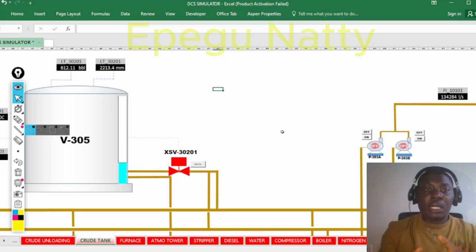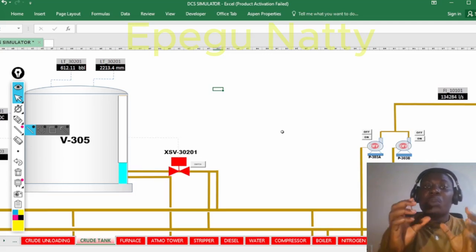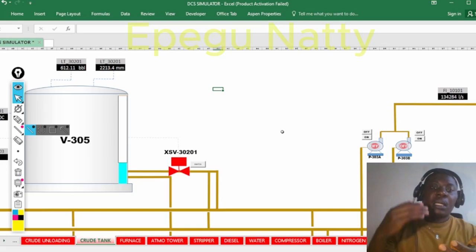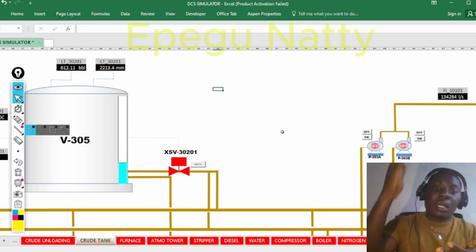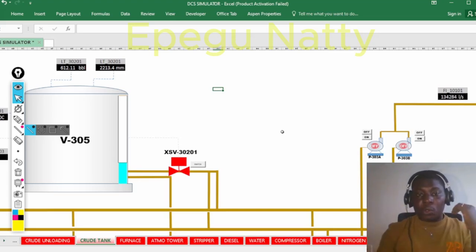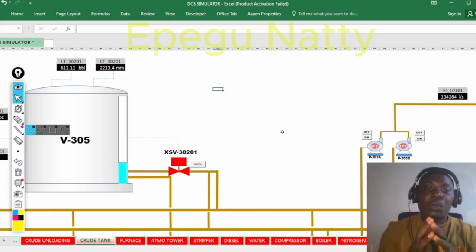So that is when calculations can be done to obtain the pump head, due to the number of bends, the number of valves on the line, the elevation of the line, and all the rest, from the discharge and also the suction. When this calculation is done, the head will be obtained based on the formula we just calculated here.